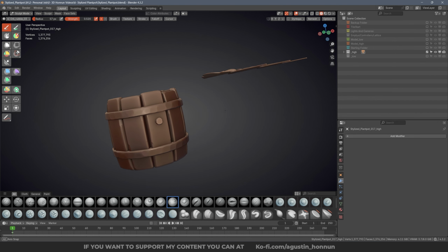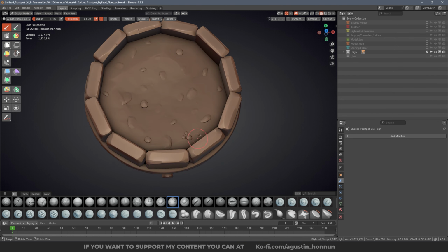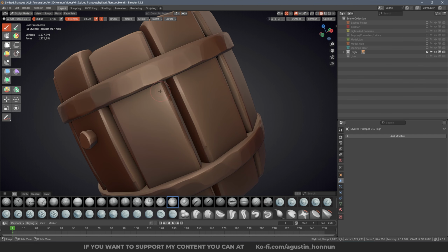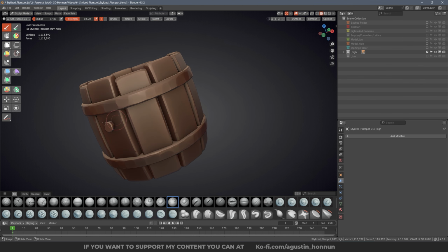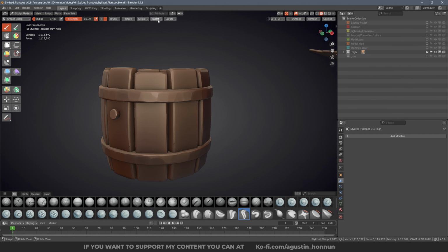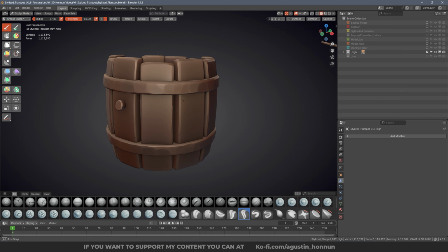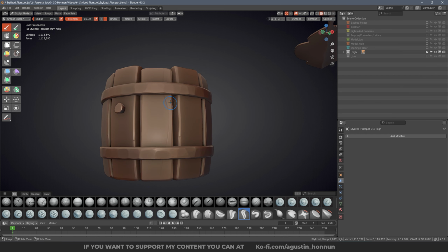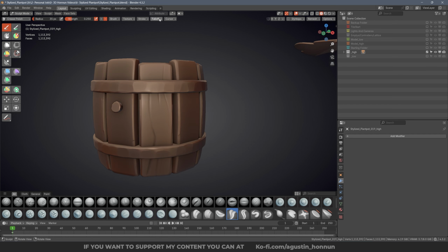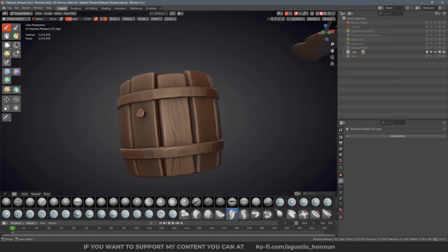We have a base for this plant pot, but we need to sculpt the wood here. These planks can be sculpted as you want. For example, use the crease sharp brush and change the fill of it to sharper. You can enable the pressure of the pen and drag some lines. You can do something simple like this. Play with other brushes like the crease polish. By the way, there are many different ways to do a wood sculpture,